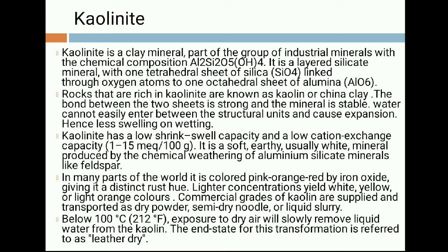The bond between the two sheets is strong. Means this silica and alumina sheets both have a very strong bonding between them. The bond between the two sheets is strong and the mineral is stable. Water cannot easily enter between the structural units and cause expansion, hence less swelling on wetting. Means because of this strong bonding between silica and alumina sheets, they don't allow water to penetrate between them. Because of this, kaolinite has very little possibility of swelling.